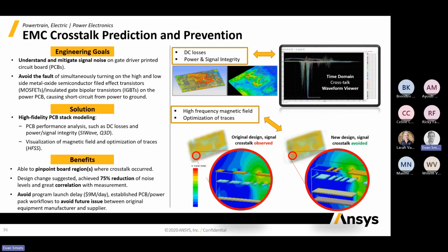So we can actually bring in the board layout from the ECAD files directly from the designer of the PCB. And then we can start adding details like all the board mounted components and the operating currents and voltages and so on. And because we can bring in that ECAD file, obviously then it's exactly like we've designed it. It's not some approximation that we're guessing here. It's the actual design that we're working with.